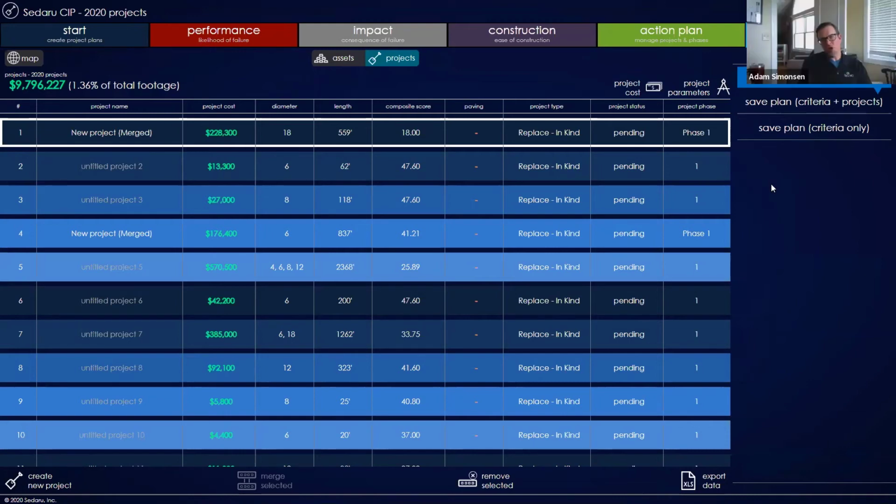Right. And when you create planning alternatives now too, you can also apply filters right from the start, so that if I want to immediately consider only a subset of my pipe and my system, I can do that. And say, hey, we'll be rolling that out soon. Yeah, basically 8 inches and higher, or a specific pressure zone you care about, or district, or really any attribute that you add to your mains layer, it can consume that. It's a simple query like is or is not, then you pick the options you want, and you are able to create projects and score assets within that specific area.